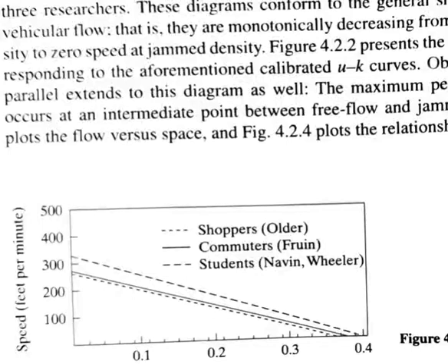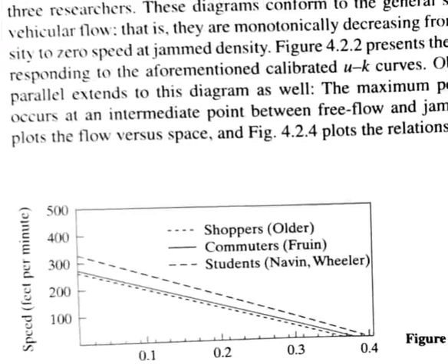So you can see that when the density is 0.4, the speed is reduced to 0. So as the density is increasing, the speed is decreasing, and that has become 0 value. So what does it mean? Yes, since there are so many people at the road, people are jammed, they are not able to move, so everything has come to a standstill, and that is called jammed density. So that particular lane is at its jammed density, meaning that particular street is completely filled with people and nobody is able to move.